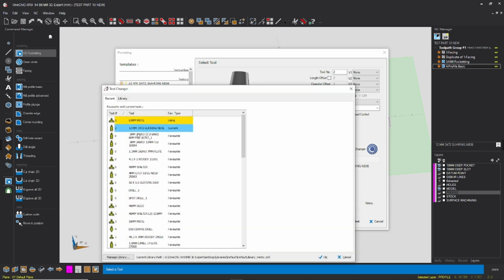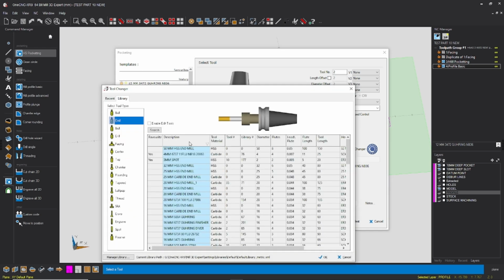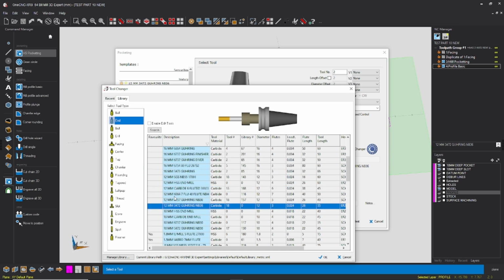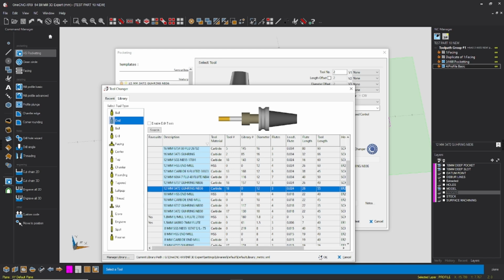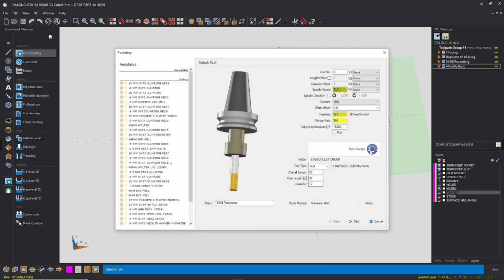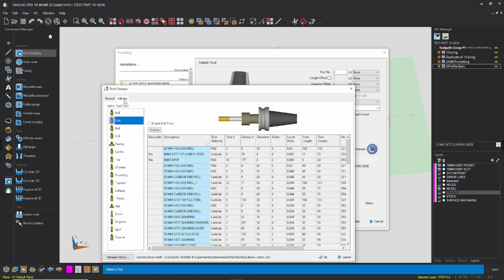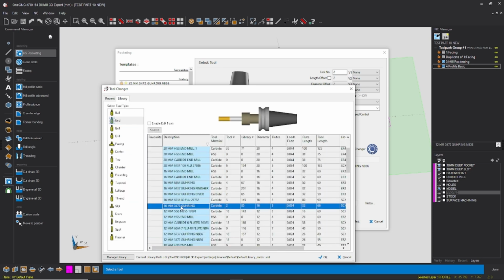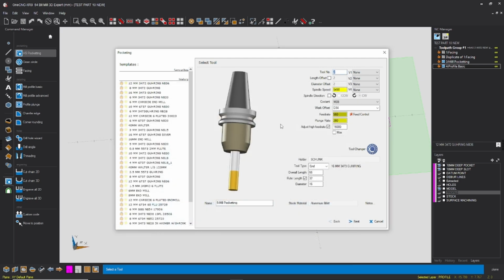Let's grab a tool. I'll tell you what we're going to do. We're going to grab a big tool, and then I'll show you 2 different ways. So this, we use the 12. No, we're not. We're going to go even bigger than that. We're going to use the 16. So it's purposely not going to be able to finish the corners because they're 6mm rads. Because this would do an 8mm rad. So let's go tool 2.